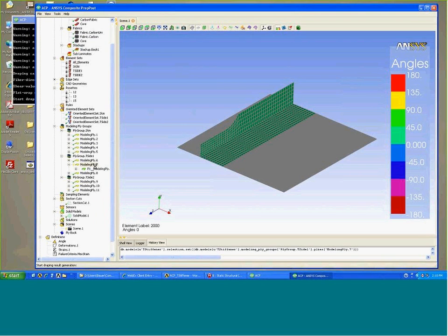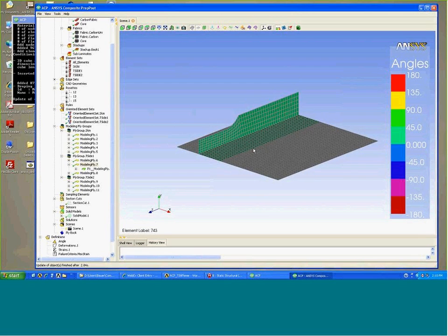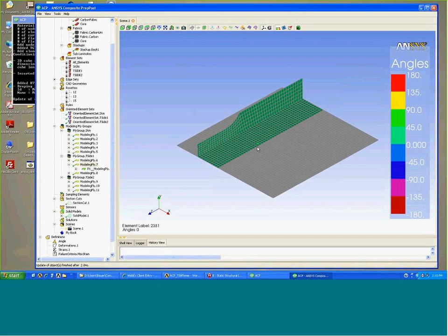So it goes through a draping simulation, and one way we can review the draping simulation results is looking at the resultant ply angles. Normally we check the orientation definition through our fiber direction toggle switch. In this case, the blue arrow shows draped fiber directions.